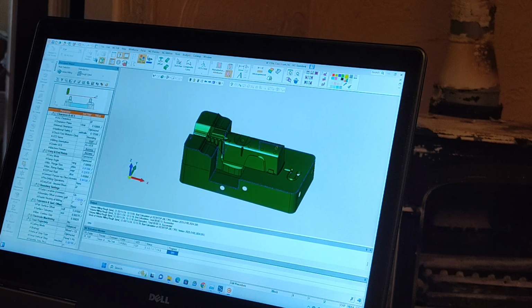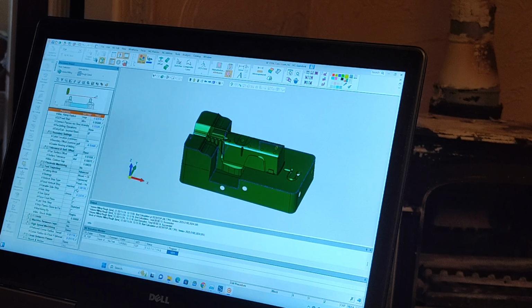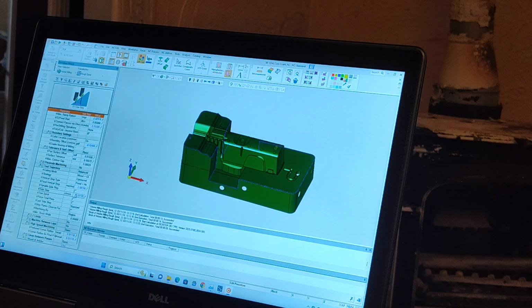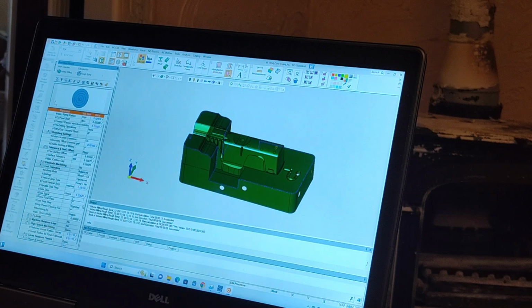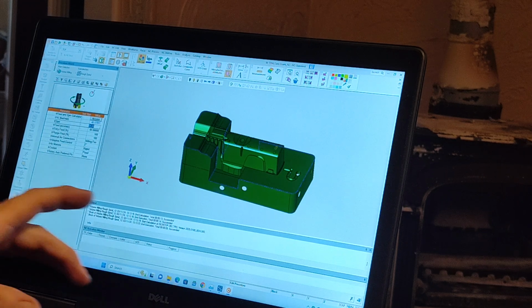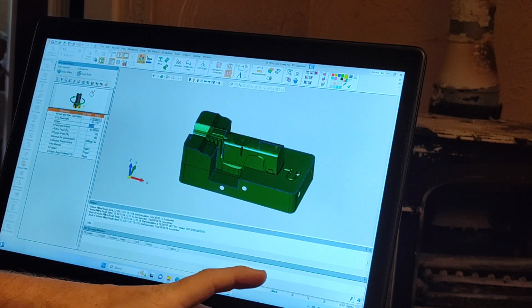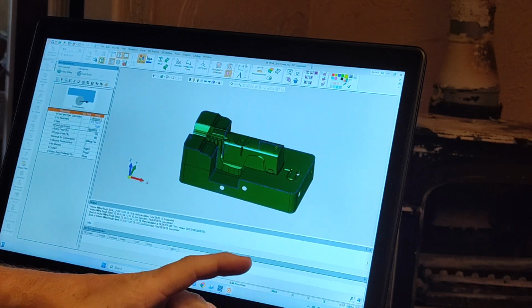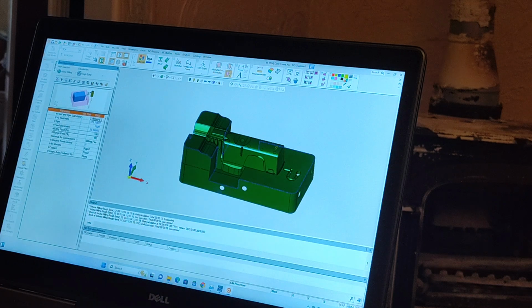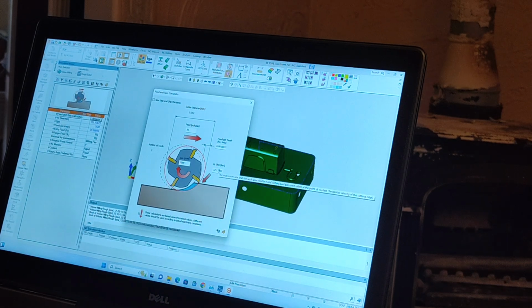And normally when I'm roughing with a ball cutter, the fixed vertical step at 3% is still a good value, but the side step for roughing with a ball cutter, I'll normally do 10%. Okay, and then check the RPM and feed rate. So we'll do 7,500 and 20. Check the surface speed.